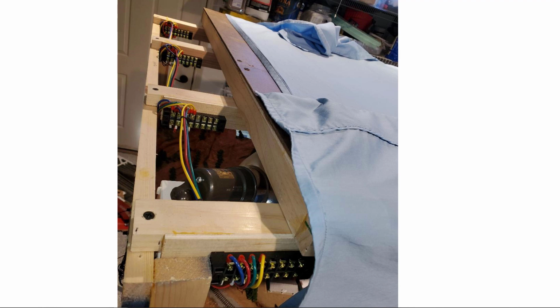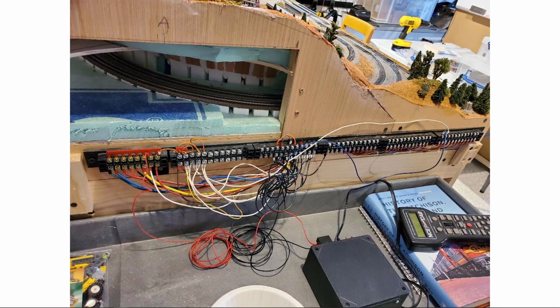These LED strips, or these terminal strips, are kind of out of your view when you're looking at the layout, but the LEDs themselves are definitely out of your view because they're behind those little vertical pieces of plywood. Back to my wiring. Here's the mess, and just to explain that mess a little bit, on the left end you see a red jumper bar, then an orange wire carrying that over to another jumper bar to other jumpers. Those were all of the individual feeds for all of the isolated sections of track throughout the whole layout.